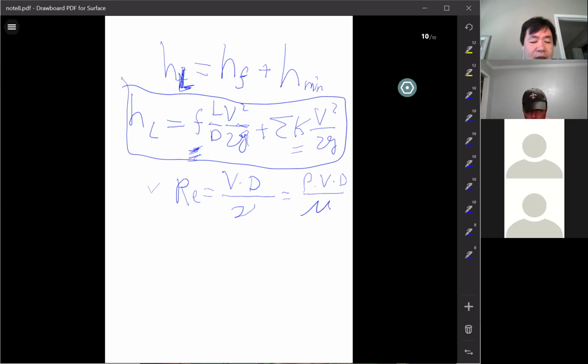It is also related to the roughness of the pipe. We're talking about friction, so what material the pipe is made of dictates the surface roughness. The y-axis on the right side of the diagram is called relative roughness. It's k over D. So this is the right vertical axis. Let me send you another table. Now this is very practical. Different materials have different roughness. Let me show you a table in the textbook.